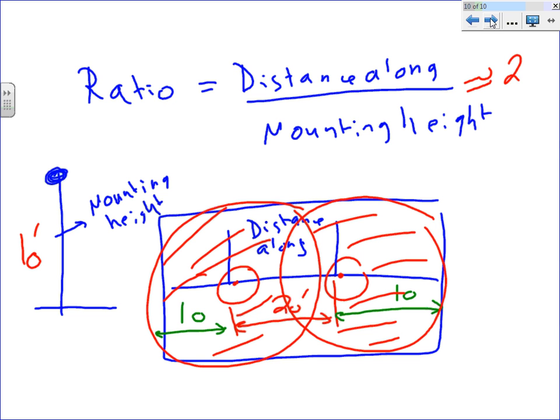The only thing I didn't talk about, guys, is that all these formulas, Spencer, are for horizontal foot-candles. If you read the book and say, what do they mean by horizontal? Horizontal foot-candle is right here in front of you. Vertical foot-candle is right on your screen. Now what if you move that into a different than 90-degree angle? That would also be vertical. So horizontal is when it's horizontal. Anything other than horizontal, 90-degree, 120-degree and so forth, that's vertical.